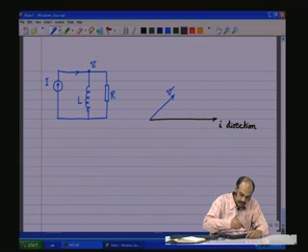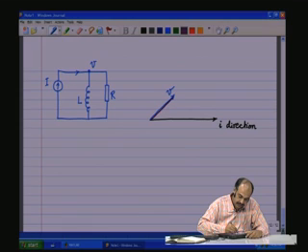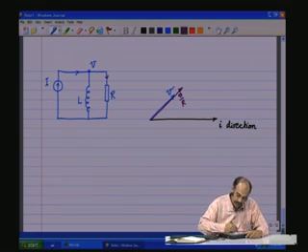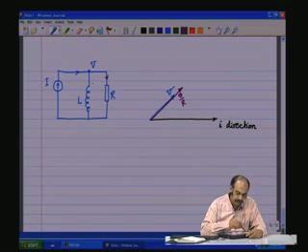Now, along this voltage space phasor, in phase with that is going to be V by R, which is the current here, and then there is an inductance coming in the picture, and as we are talking of solving the Kirchhoff's current law, this is going to be the susceptance, inductive susceptance, which is minus jB, and therefore, it has to be minus 90 degrees.